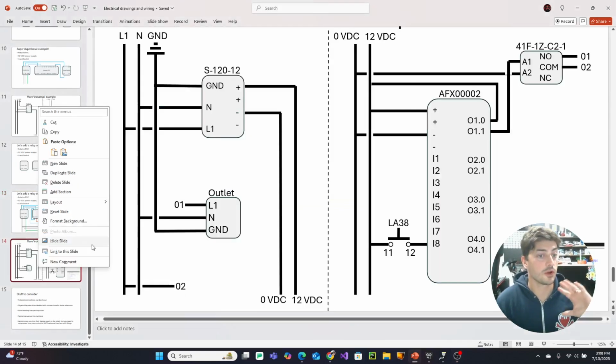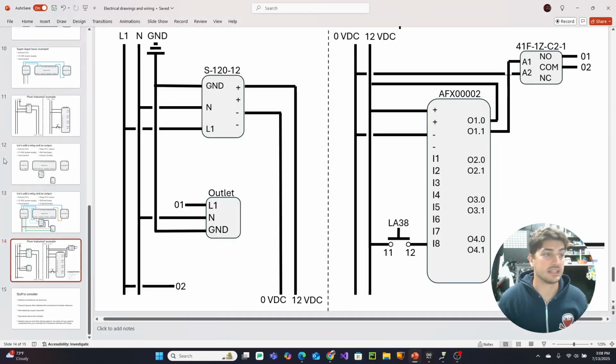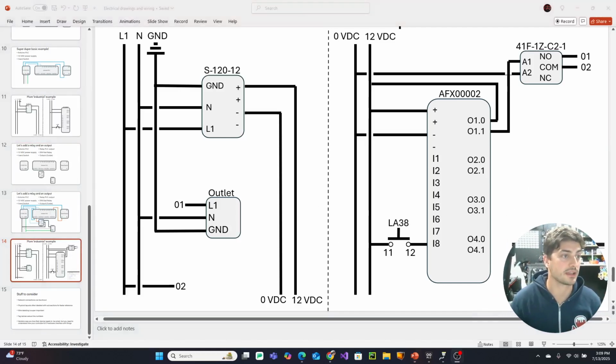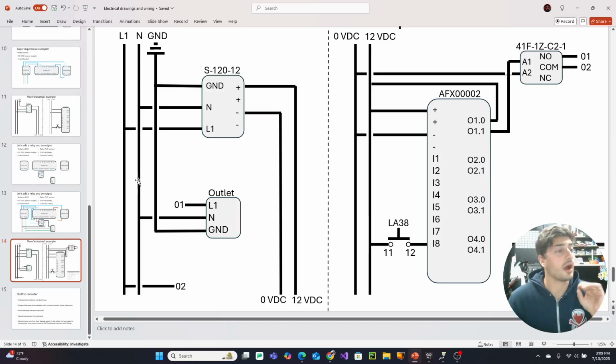Now, same as before, let's take a look at how this would get represented in a more industrial controls package drawing. So let's take a look at what's changed. We still have the power feed on the left going through our 24-volt power supply, which I know I called out as 12 volts in here, but it's 24 volts on my bench setup. Sue me. Anyways, I did something interesting that I think is useful to call out on this tutorial: I labeled two wires with numbers, O1 and O2.